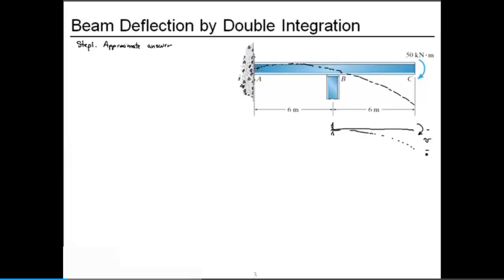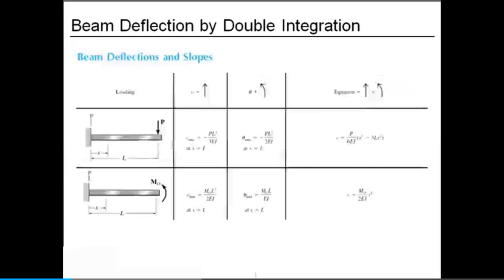And so let's predict the vertical deflection for this situation. It will be an underestimate, but I picked this geometry because it's represented in the front cover of our textbook as the following situation. So we have a way to calculate the peak deflection of a cantilever with a couple moment at the end by using this formula, which, by the way, was derived using double integration or one of the other methods for predicting deflections of beams.